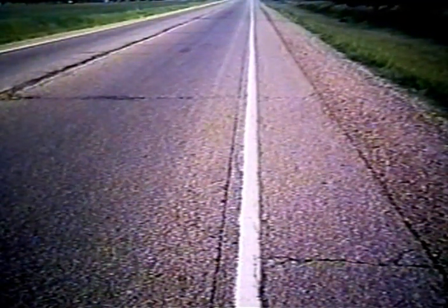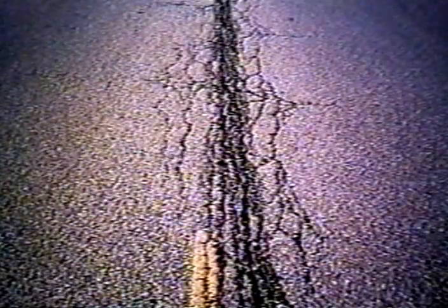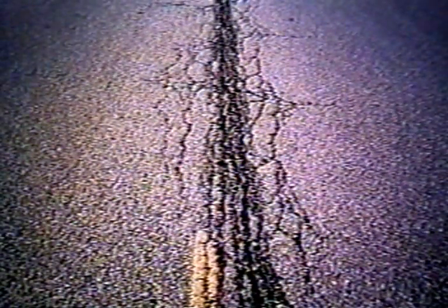This points out something that's helpful, I think, in thinking about longitudinal cracks. We talked about the movement that's inherent with transverse cracks when you have the pavement expanding and contracting. You really don't have that much movement in longitudinal cracks because you don't have the width of pavement there to expand and contract. So these are generally easier to fill and seal than your transverse cracks are. But if we don't keep up with some preventive maintenance on transverse and longitudinal cracks, you see raveling start to develop. Here's a case of very extensive raveling along a centerline joint or a longitudinal crack.